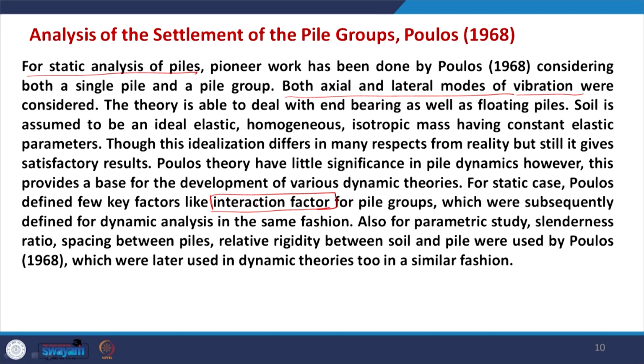So, one thing is the interaction factor, the other thing is the parametric study. Poulos considered, when analyzing the pile groups, what is the spacing between piles and what is the relative rigidity between soil and pile. All these issues were later considered by those who carried out the dynamic analysis.